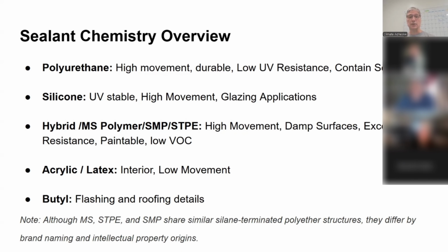And then silicones are UV stable. They can handle a lot of movement. You can use them in a lot of applications. They'll use them for a lot of glazing. You can use them in masonry systems, concrete systems, etc. They tend to be a little more expensive than some other products.